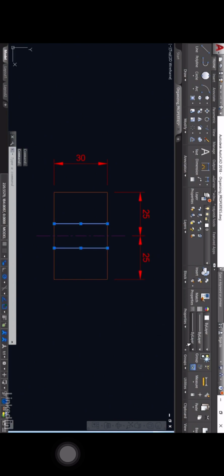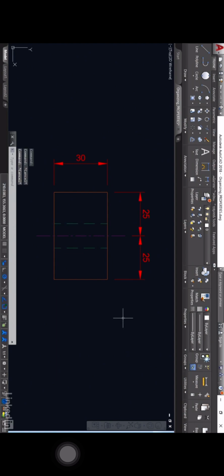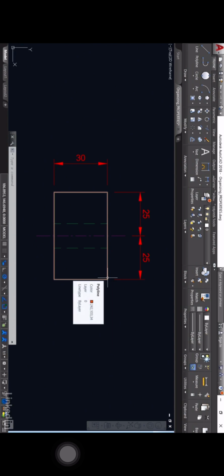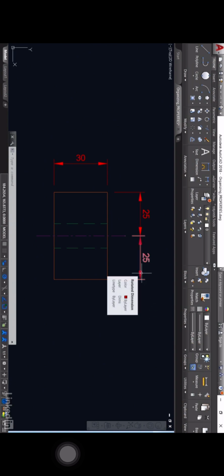So what I'll do is I'll change the line type property to hidden, and they go dashed, and then I might give them a different color, let's say green, like so. Hit Escape to deselect, and now you can see I've changed all of the properties of all of the objects in that drawing into different colors. Now, the different colors don't define the layer. That's also on layer 0, but it's got a different color, different line type. However, here, they're adopting the color by layer because they're on the layer dims. They're not on layer 0. So that's how you can change all of your properties in your AutoCAD drawings using the properties palette, and also perhaps changing the layer as well of an object to give it different properties that are adopted with the by layer setting.